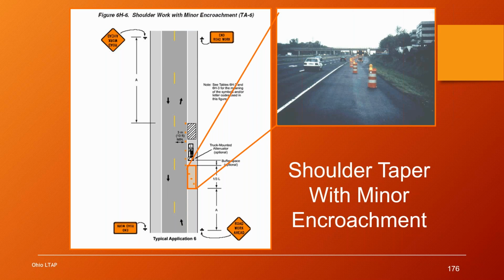So you have to put some thought into what your standard will be as far as how wide of a lane you're going to have left over for the traffic to drive in. Especially on a 2-lane road, you don't want a situation where you made the lane too narrow and they're getting over into the other lane and cause a crash.